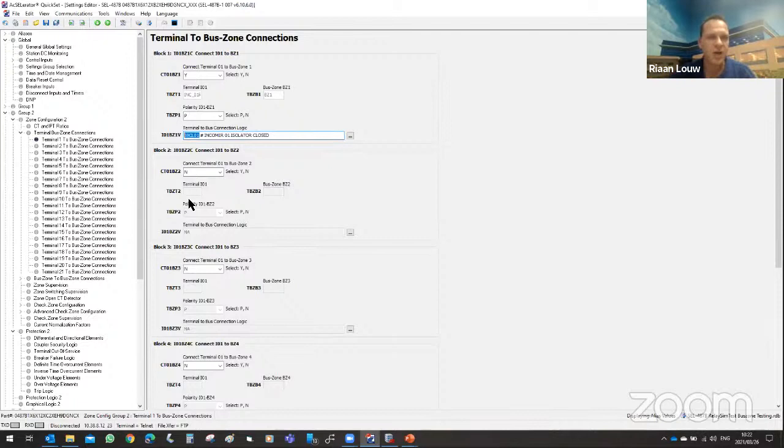The one is the hardwire one, which we are not using, and I'm showing that so you have the idea in the back of your mind that this is an application where you can have the hardwire logic still existing in the relay, but in parallel, if configured from the onset, you can have a virtual set of logics which test exactly the hardwire functions, but just virtually with the application of the GOOSE.